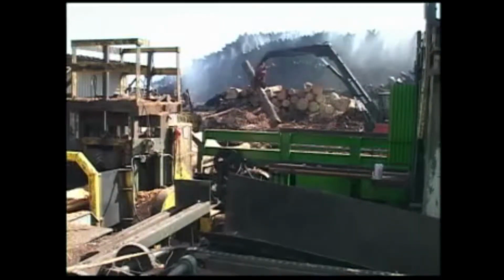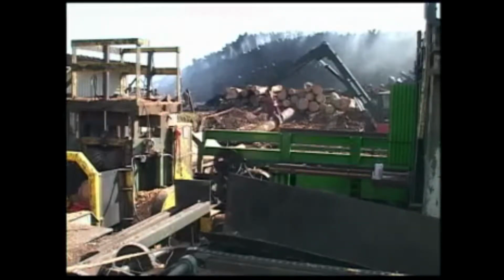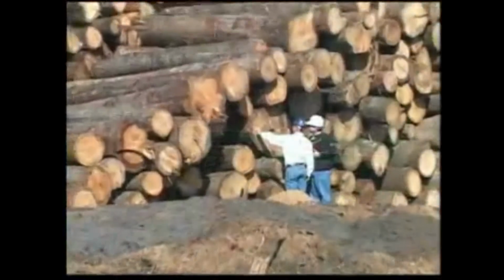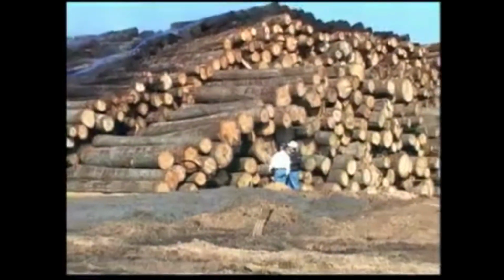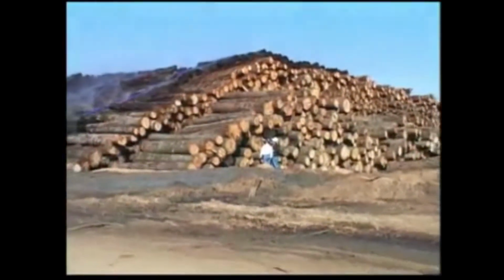Wood, by its nature, is always adjusting to its surroundings. Like a sponge, it will absorb moisture back into its dehydrated cells when given the chance. Wood that is dried to 7 or 8% moisture is stable and predictable. Over 14%, it becomes unstable and swells.